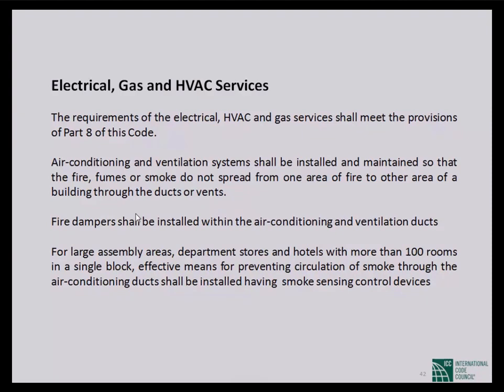So if you like to stop it, you put some damper according to need, for which floor's air you like to move and which air you do not like to move. So you have to be very careful about the ventilation, air conditioning, and the smoke ventilation system. All these ventilation systems have to be designed simultaneously, and operation will be very critical.